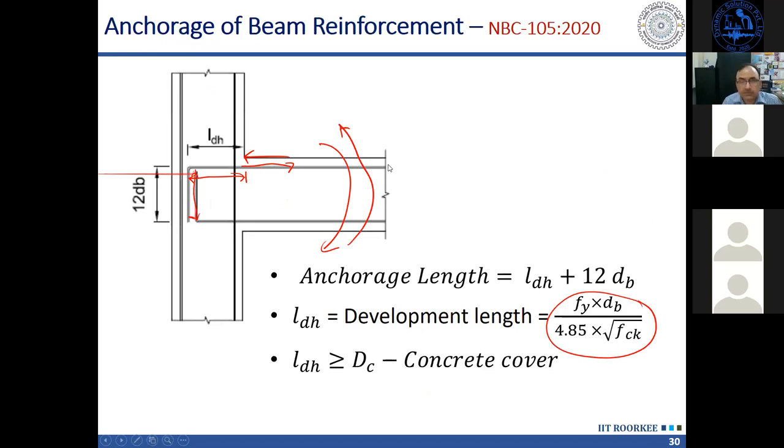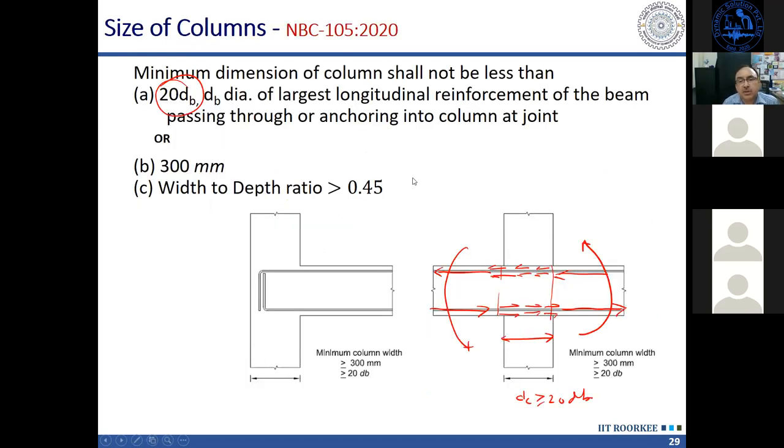So when I'm applying, or maybe even better understood here, I have a shear force equal to Vc which is acting here. In the joint, what am I getting? I'm getting the shear force. Actually, if the earthquake is causing anti-clockwise movement, the column shear will be opposite in this direction, what I have shown. Okay, so this will be the shear force in the column, Vc.